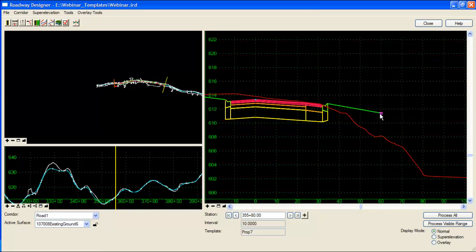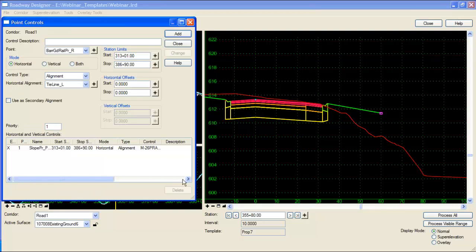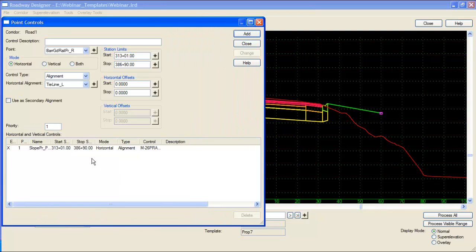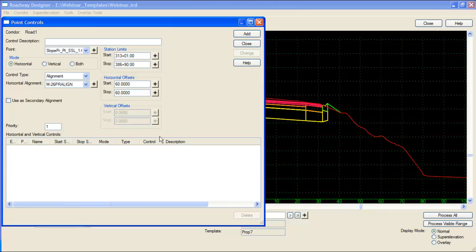That's not exactly ideal, obviously, because it's not touching ground. But you get the idea with the point control. If you assign it, you'll see that now it has a purple box around it, and that's the whole point. If you select it, you'll see the point highlights white, and you'll see that it has a purple box around that point, and that indicates that there is a point control active for that particular point. And I'll go ahead and delete that since it's not necessary.